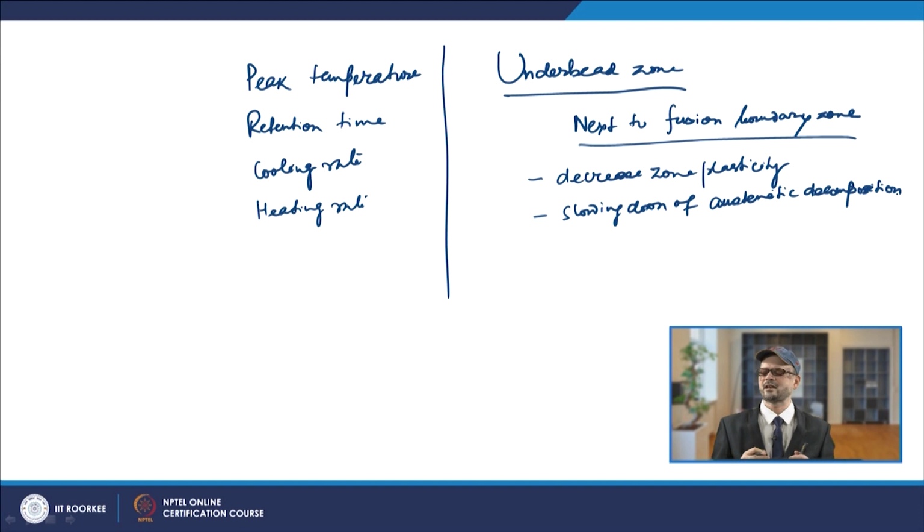Sometimes that favors ferritic formation or ferritic precipitation, and a different type of microstructure is also formed. That is the outcome of the coarse primary grains. Then, if you have growth of the grains, you have increased susceptibility of steel to cold cracking.